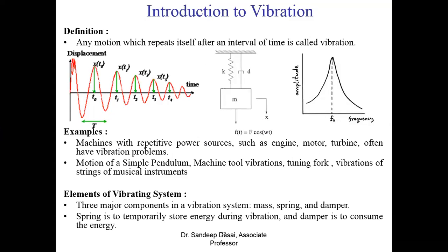Unbalance is not the only cause for vibrations. Vibrations might be caused by a number of other reasons. But yes, unbalance is one of the reasons. Due to that, the system will be subjected to vibrations. You must have experienced this when we conducted an experiment on balancing of several masses rotating in different planes. When the masses were not balanced, the system was vibrating. When they were balanced, the system vibrations were reduced. Right?